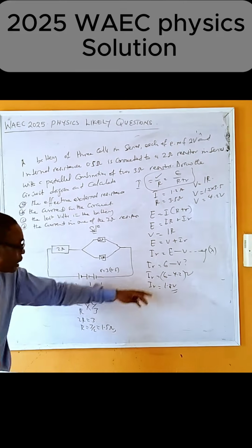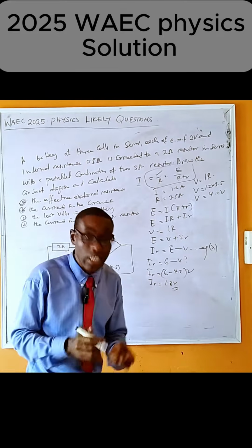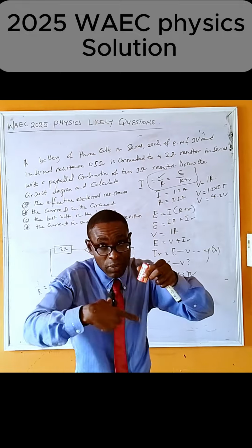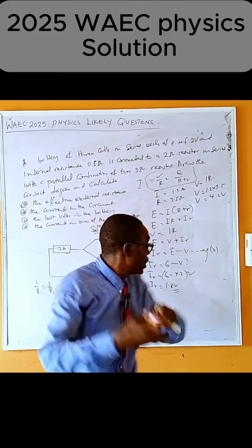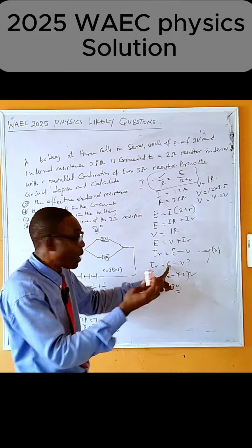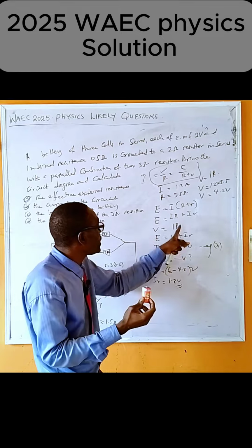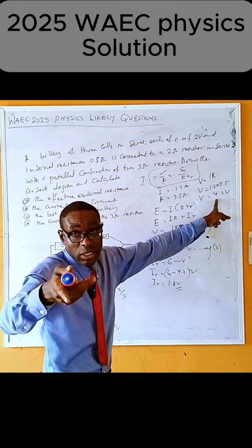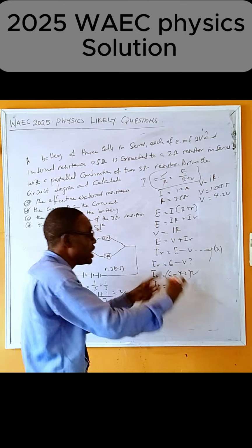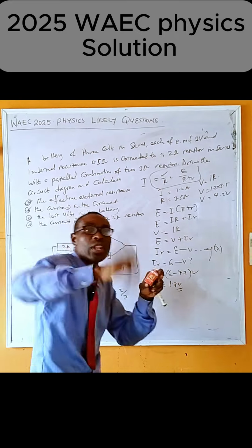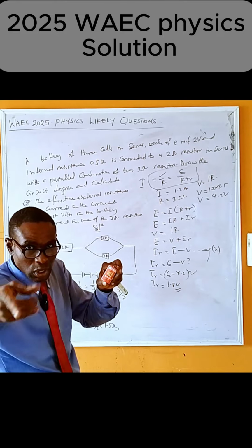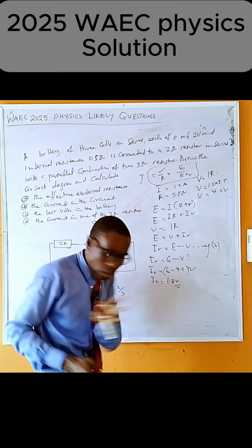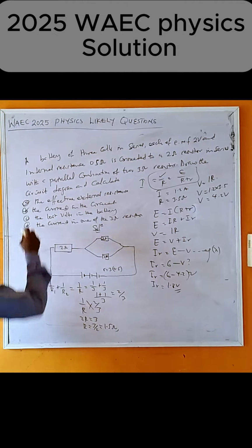Now, I told you why I was explaining this: when you take this battery, this is what the potential difference is. Let me say this is the battery. But the potential difference read after powering something must have lost voltage. So loss of voltage is equal to the EMF of the cell minus the terminal voltage when you use it to power something. The difference is what this battery lost. So this is the loss of voltage, meaning that we have solved this one as well.